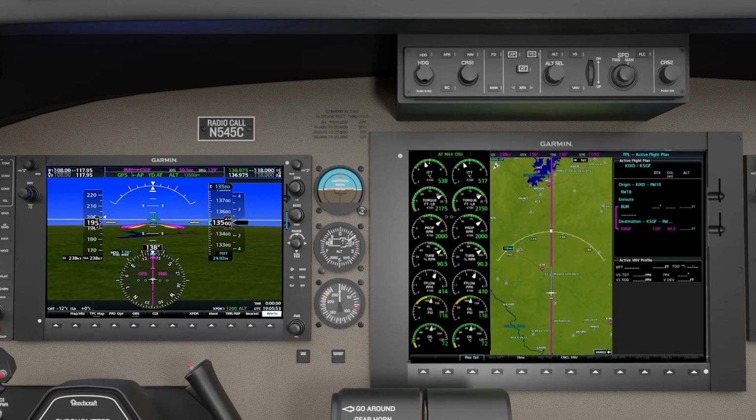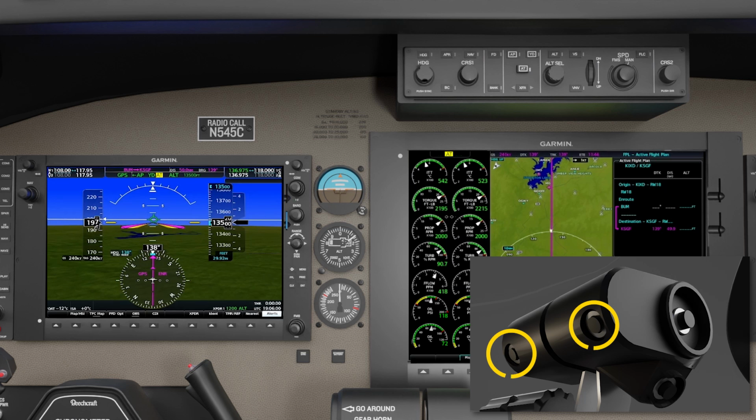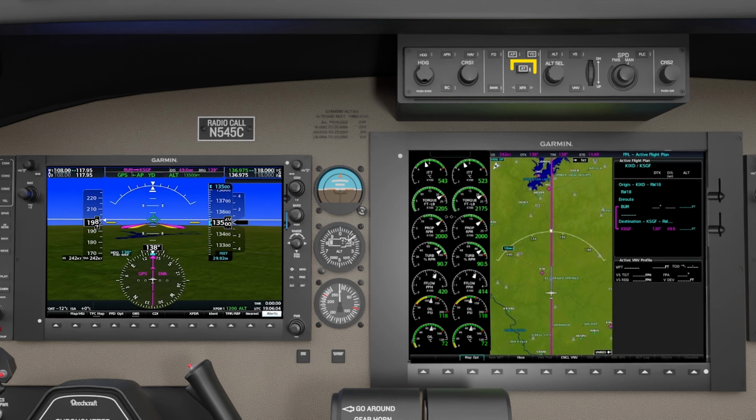An abnormal disconnect occurs when the autothrottle disconnect is not initiated by the pilot or by normal sequencing of the AFCS. An abnormal autothrottle disconnect will be enunciated by a yellow and black flashing AT in the AFCS status box and the autothrottle mode enunciator, and a repeating autothrottle aural alert. To acknowledge the disconnect, the pilot must either press and release the autothrottle disconnect button on the power levers, or press the AT disconnect key